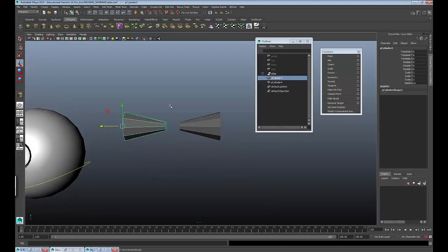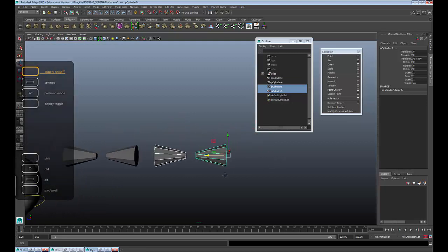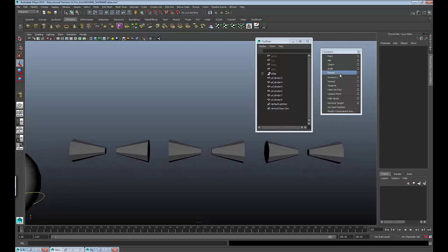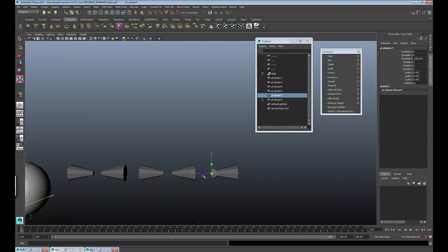All right, so we've got these two shapes. As I was mentioning, there's a bunch of different types of constraints that we can use here. The parent constraint acts just like parenting an object. The only thing it doesn't do is scale. It does translates and rotates, but it won't scale the objects together by default. I could add what's called a scale constraint, and then it'll behave as if all of those elements are connected. But we'll save that one for later.